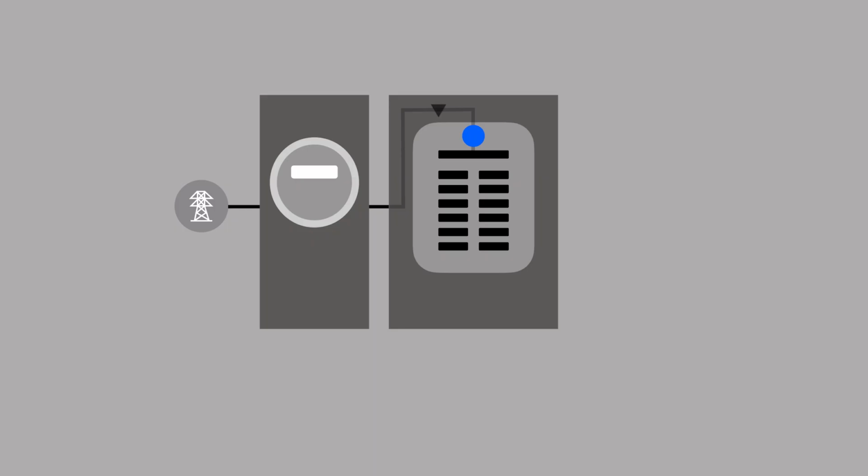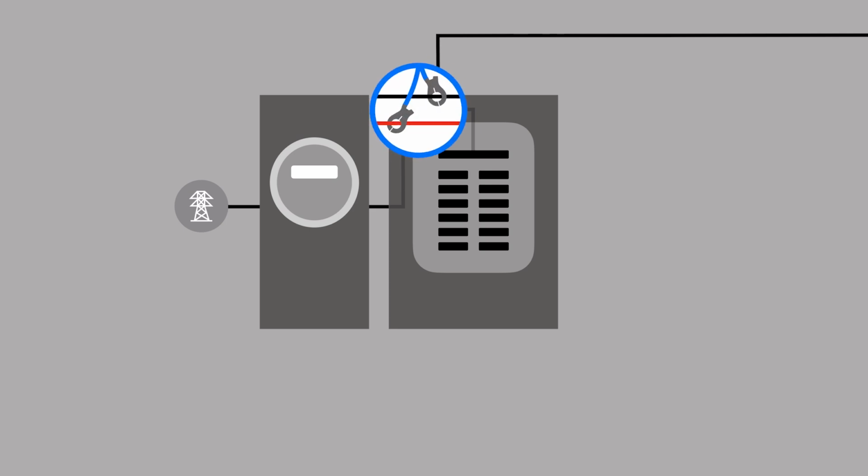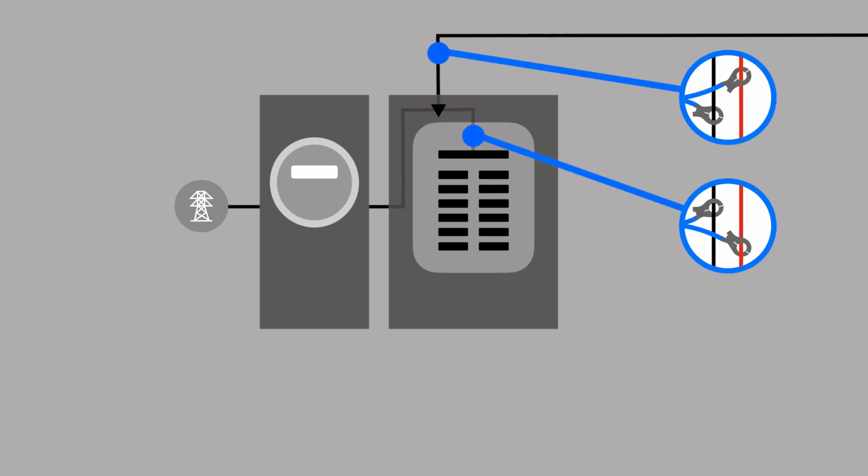If any line-side taps are present in the system, site CTs must be installed upstream or closer to the utility meter than the taps. If taps are installed in a position that prevents current transformers from being installed upstream of their connection point, two sets of CTs can be used to monitor both the main panel feeders and the tapping conductors. When multiple CTs are being used to monitor the same phase, Y-splitters can be used to combine their readings.